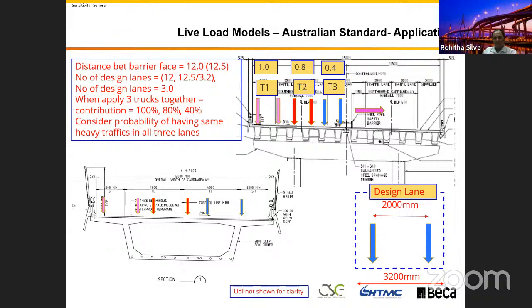You don't want to produce hundreds of thousands of load cases and what we call the envelopes. You just check your load cases first, and you will see that one is supposed to be on the top of your envelope. The rest will be underneath that one.